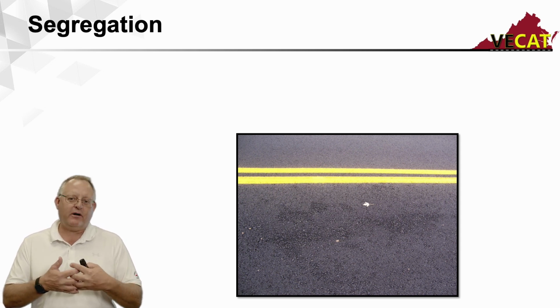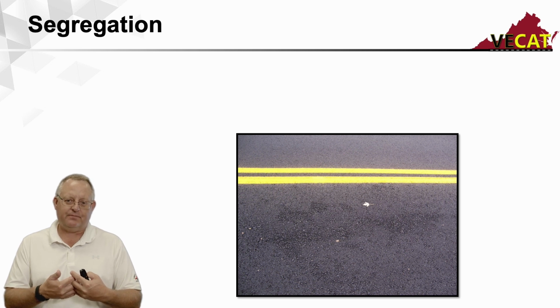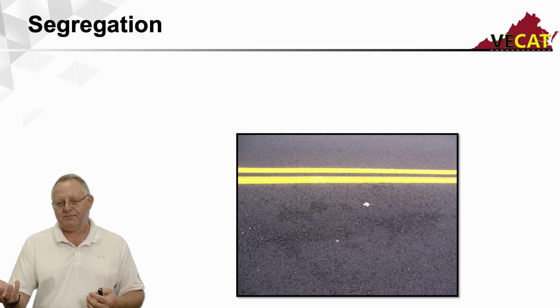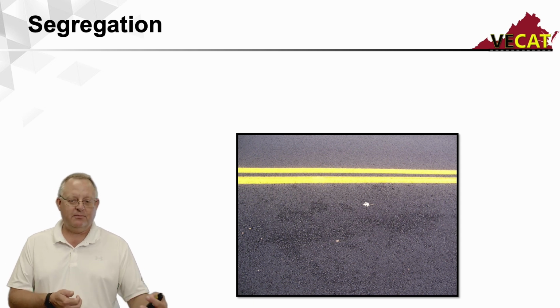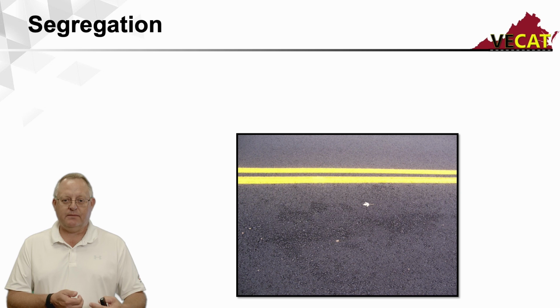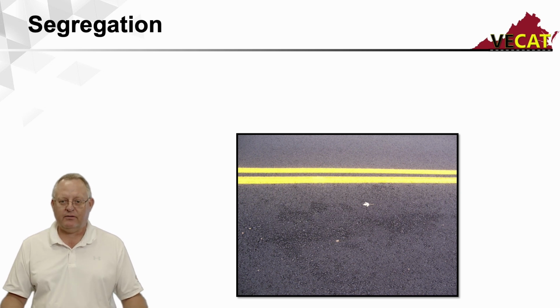So you no longer have fine and coarse material together. What's going to happen is where that coarse material is, water will get in there, air will get in there, you'll get premature cracking, and then you'll get potholing. So that's what we're trying to avoid.